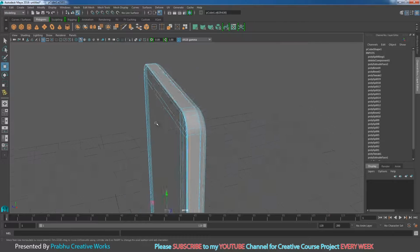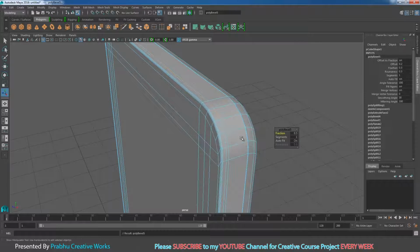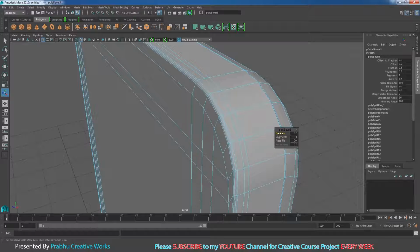When the edge loop is selected, shift right click and choose bevel edge. So you want to decrease the fraction amount to 0.05. Same thing for here.